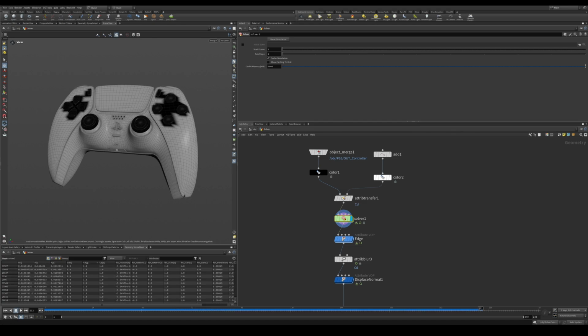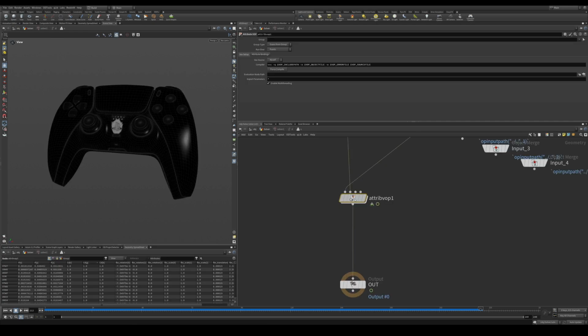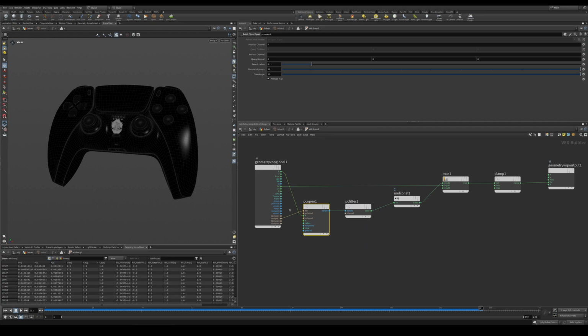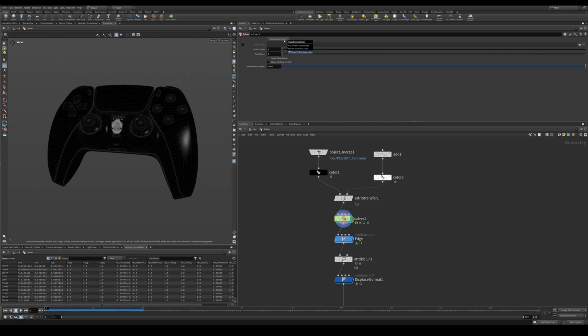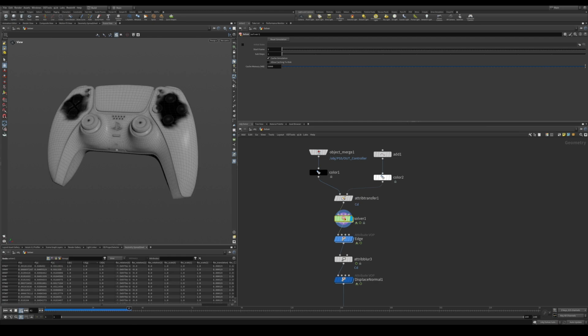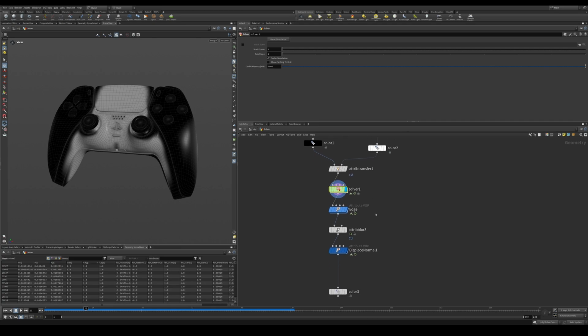These parts are not being finished through the spread, and that has to do with the point cloud open. It doesn't have enough points. So if we go to the point cloud open, we select the number of points. We put 60, kind of like we did before with the Pyro Source Spread, and press play now. Oh, we've got to go back. So with VOPs, we always have to go a level up in order to see our result. So reset simulation, and now we can see it wrap around. And that's it for that solver setup.